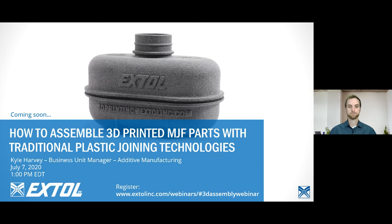Great. Another question here. What durometers do you prefer for the caps? Is there a specific one? So the caps themselves, if you print TPU solid, it's in the 88 to 90 Shore durometer. But I've also printed, say, thin-walled portions with trapped TPU on the inside.